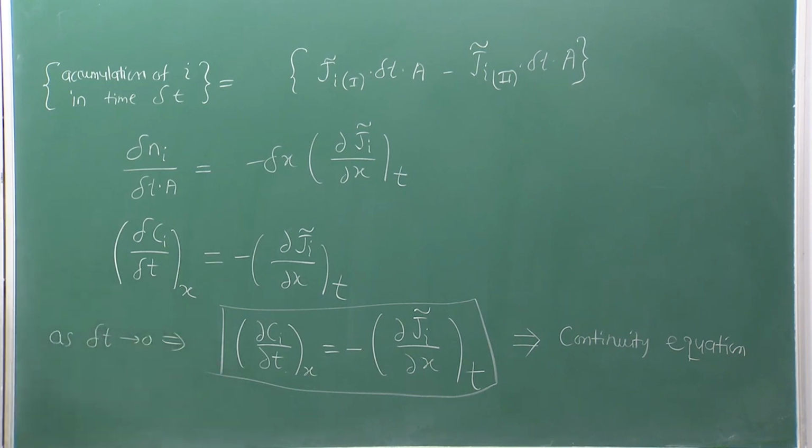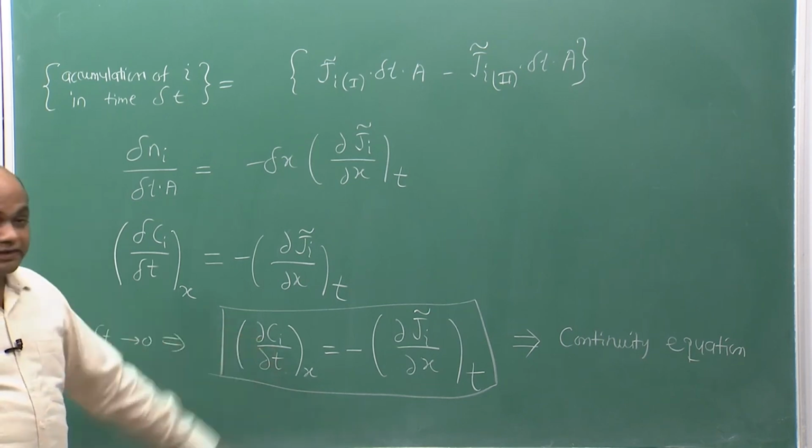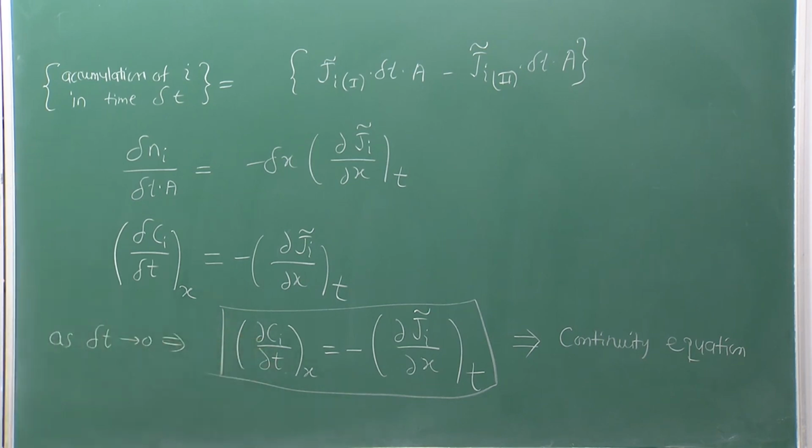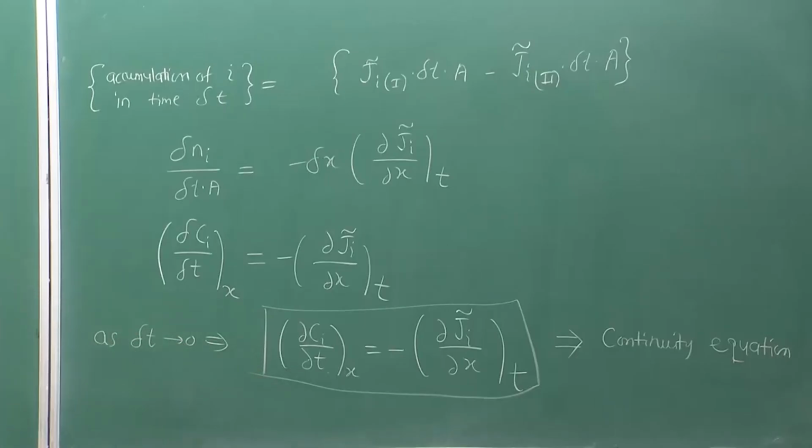Typically, in the diffusion in solid that we consider, especially when the diffusion is defect mediated, like for example, vacancies, there may be production of excess vacancies or loss of vacancies to the sink, and that might affect this term C I here, because it affects the site fraction of species I. So, in that case we need to also consider the rate of production or rate of loss of the particular sites or vacancies.